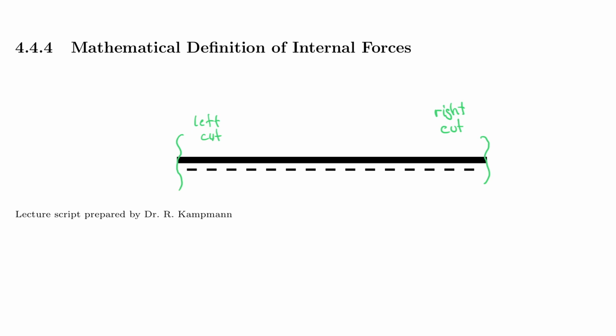And the first thing I'm going to start with is my vertical forces. So I have a vertical force on this side and I have a vertical force on this side. I also have horizontal forces, and that applies at both sides. And I have a moment on both sides. This looks like that. Now, on the right side, I have a normal force that points to that side. On the left side, it's pointing in this direction. Then I have a shear force that goes in this direction and a moment that goes in that direction.